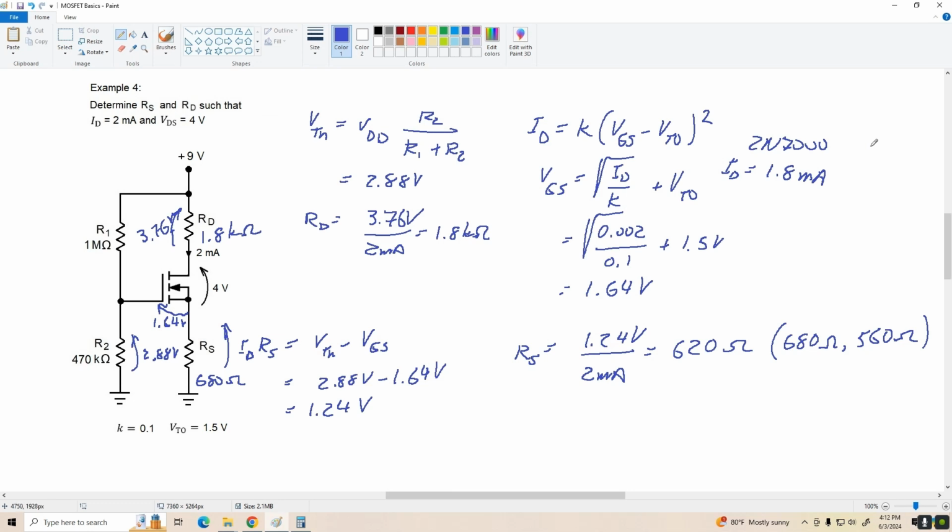And then the BS170s that I tried all came up at around 1.5 milliamps to 1.6 milliamps. So apparently the BS170s have a slightly smaller K value than the 2N7000s, but you couldn't tell that by looking at the data sheets. But based on my results, that's the case. And if you try this, maybe let me know how your results come out.